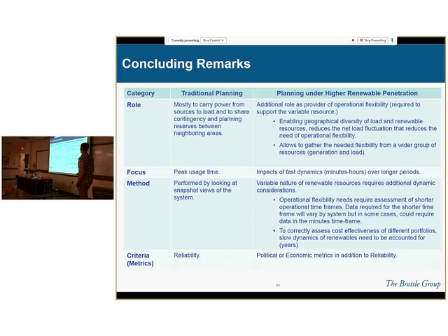So just to conclude, planning under deepening penetrations of renewables requires considering a finer granularity and considering the unique characteristics of those resources so that when we do these planning studies, we capture the value that those projects can bring to integrate renewables. And that means looking at the time or the uncertainty that renewables bring through finer granularity studies and developing metrics that can assess the value of flexibility and how transmission can bring additional flexibility to the system.